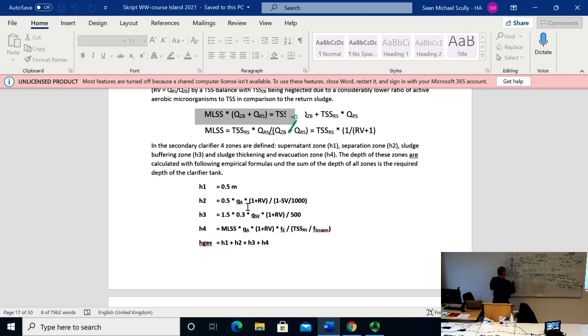This QA is, because you have, as the effluent, you have those 100 liters per person, and you have 91 persons. So you have, and their peak flow is 160 liters, because we had this factor of, 150 liters, no? Because of a factor of 1.5.